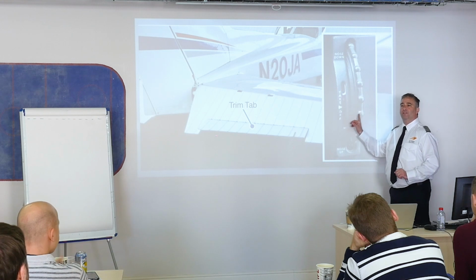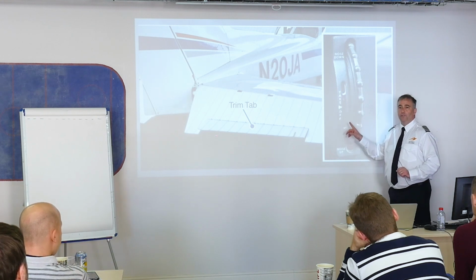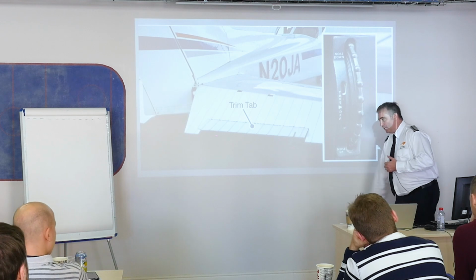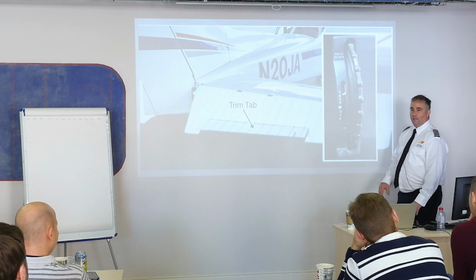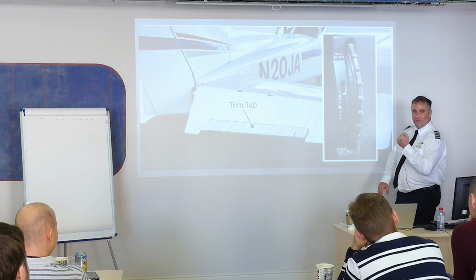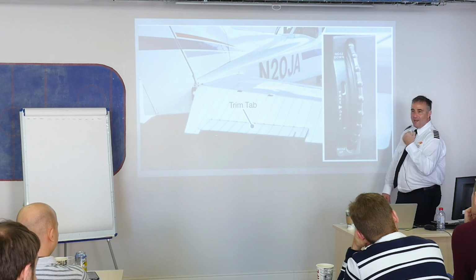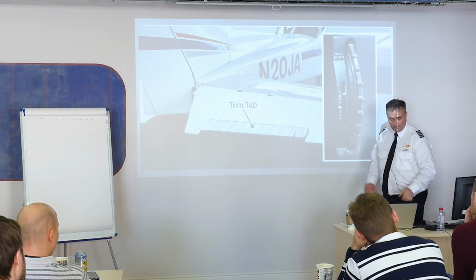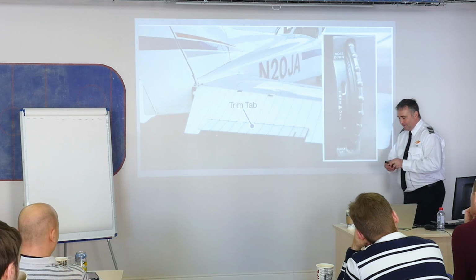But you can't use this to fly the airplane. So don't roll the wheel and then expect that it's going to make me climb. You set the climb with your yoke, and then if you have control pressure, you relieve the control pressure. All right, so fly these things properly.